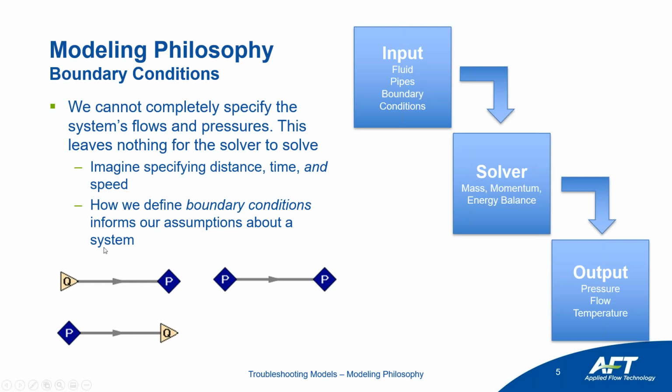So as we get into scenarios and we start tweaking the system, what if we added a valve in the middle, for example, and the valve is half closed? Here we're assuming that no matter what, we're going to achieve that flow rate, so our pressure is going to increase, or here we're going to achieve that flow rate, so our pressure is going to decrease, whereas here our flow rate would instead decrease.